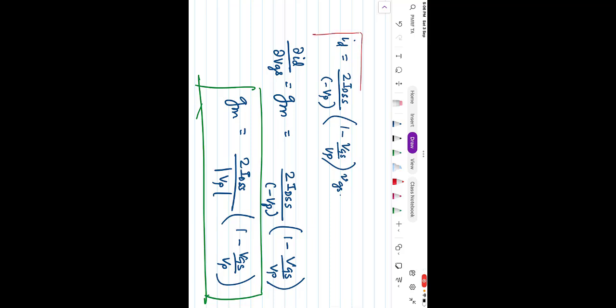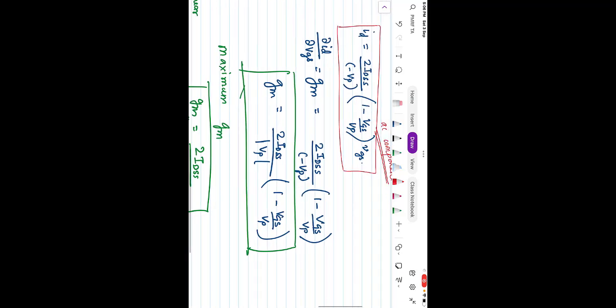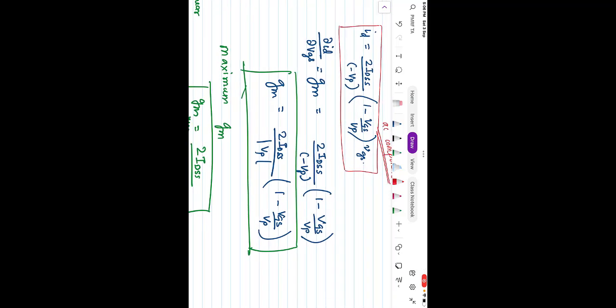Okay. So now the drain current is therefore given as the DC drain current plus the instantaneous current, right? So therefore from here we can say that the iD is basically written like this, right? Now from here, so this is nothing but the AC component that I have written. So the small id, the AC component that we had got here, this one, this is what I have written. Okay. So now delta iD by delta vGS, we can find the transconductance from here, which is delta iD by delta vGS, and that comes out to be this. Now since gm is a positive quantity, we will be using this.